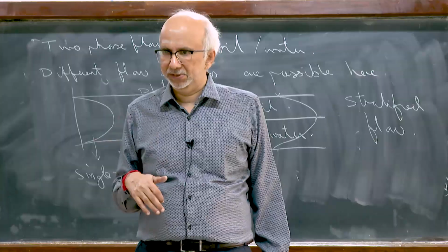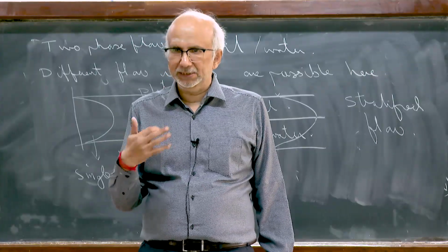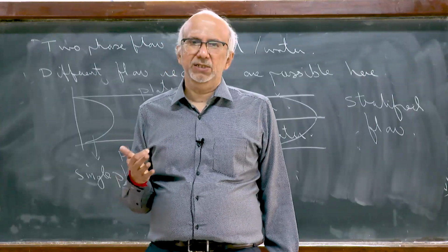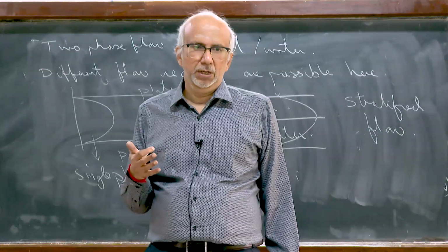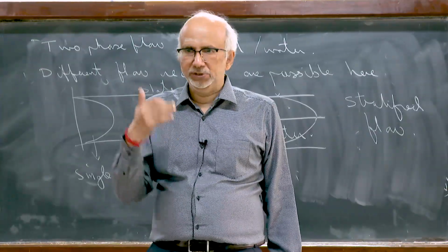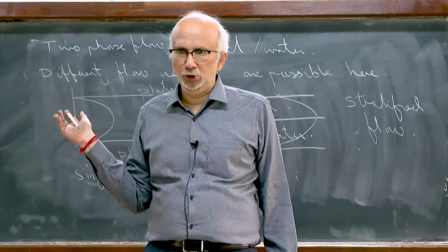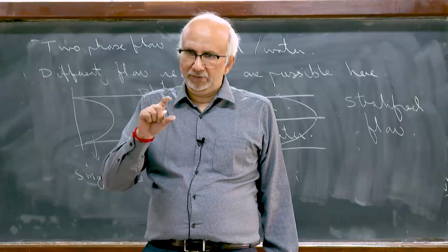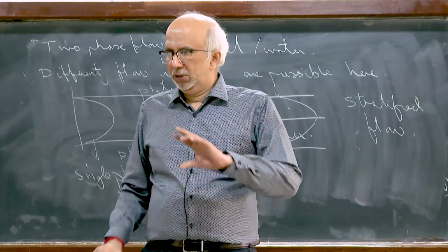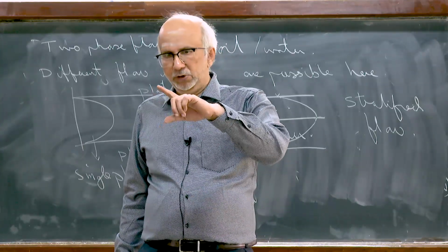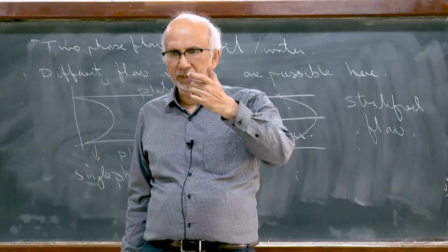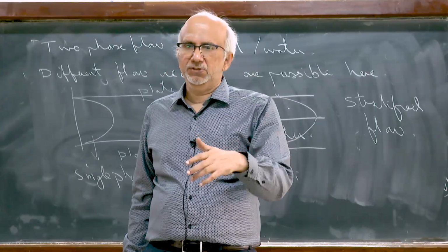That is the reason we talk in terms of dimensionless numbers like Reynolds number, Weber number. You're comparing two forces. So high with respect to what? That I have not told you yet. Whenever you have these dimensionless numbers, there's always a ratio of two forces. If I say Reynolds number high, I mean inertial force is more than viscous force.